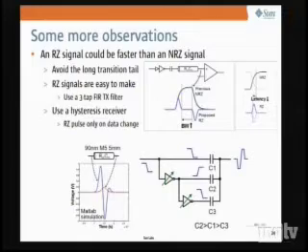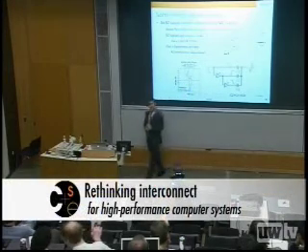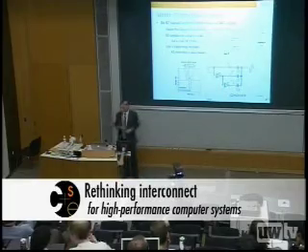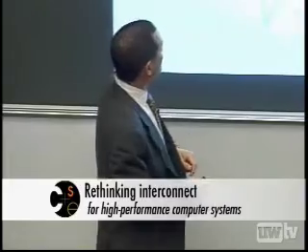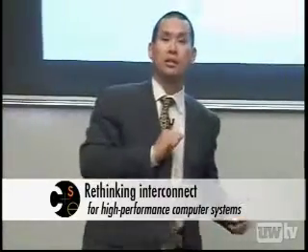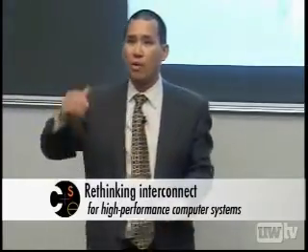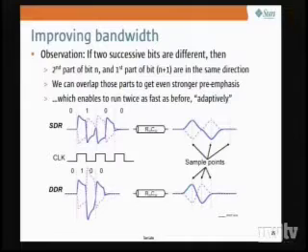And in MATLAB, you can see that that actually gives you a nice return to zero pulse on an RC line. Okay? Well, that seems somewhat reasonable. If you look at this some more, what's nice is a 1 pulse is a rising, falling, rising stage. All right? So if I have a 1 followed by a 0, that means I have the pattern shown up here. So a rising, a falling, a rising.